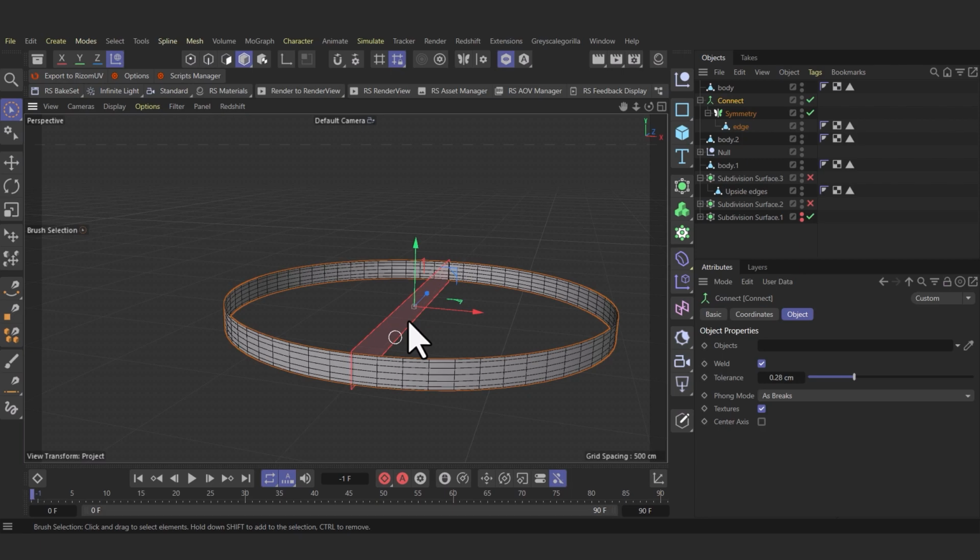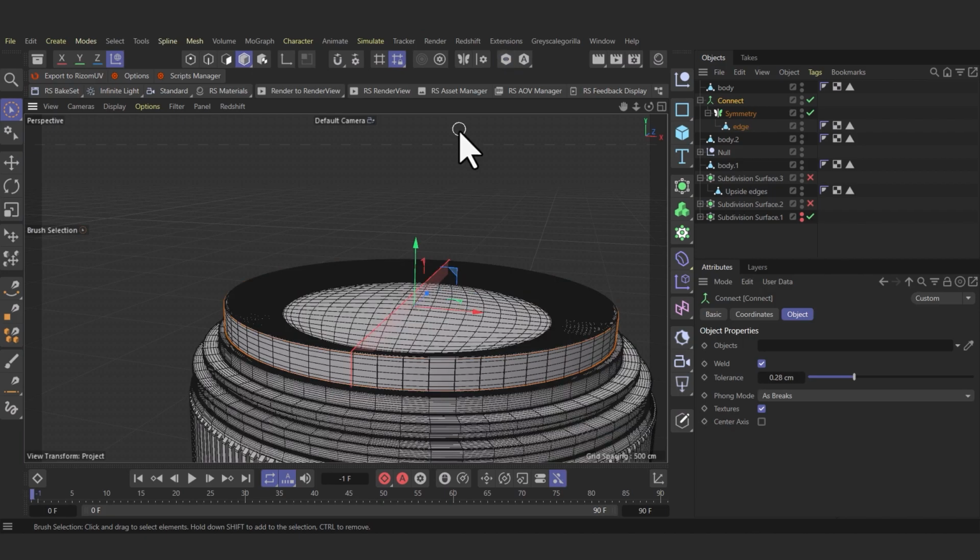The important thing is that sometimes you focus on a specific place of your model, and to connect the empty space between 2 points, you constantly change the tolerance and make it bigger and bigger. This will cause another part of your model to inadvertently stick together due to having very close points, and you will not notice it at all. This generator does not necessarily stick the distances together, but analyzes all the points of your model, and wherever it feels a range, including the tolerance value, it can be glued together. So always be careful to use it rationally and not involve other points.